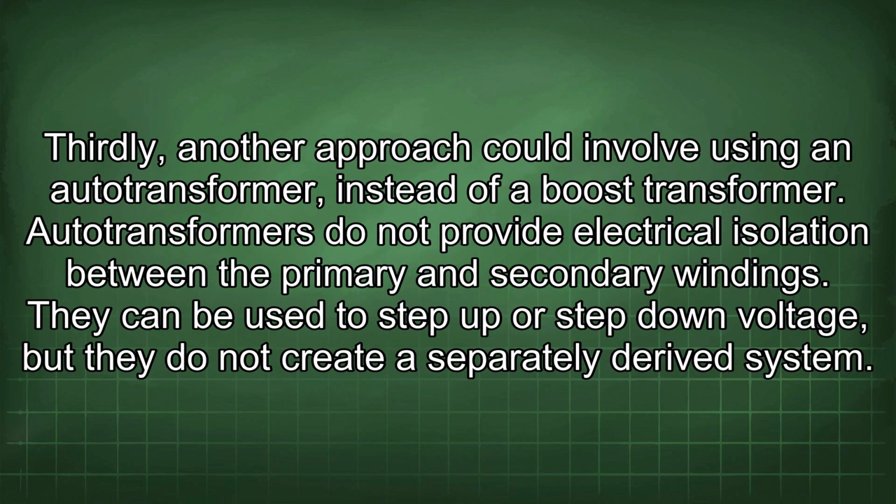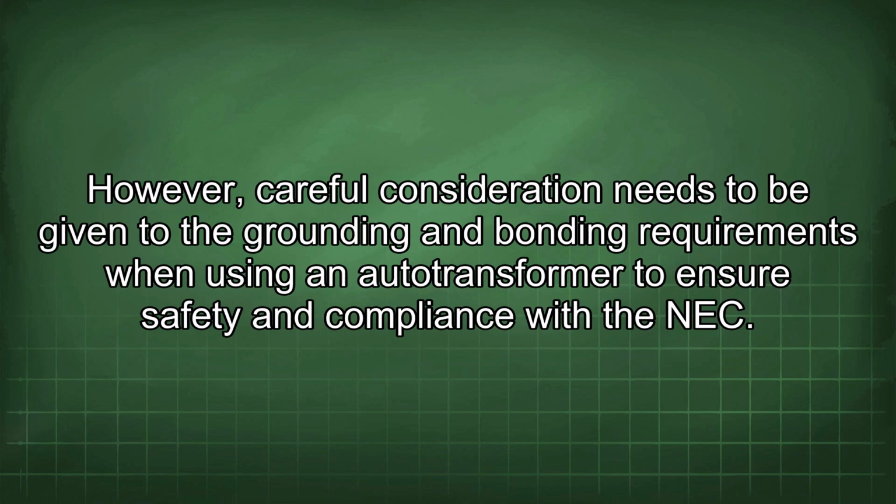Thirdly, another approach could involve using an autotransformer instead of a boost transformer. Autotransformers do not provide electrical isolation between the primary and secondary windings. They can be used to step up or step down voltage, but they do not create a separately derived system. However, careful consideration needs to be given to the grounding and bonding requirements when using an autotransformer to ensure safety and compliance with the NEC.